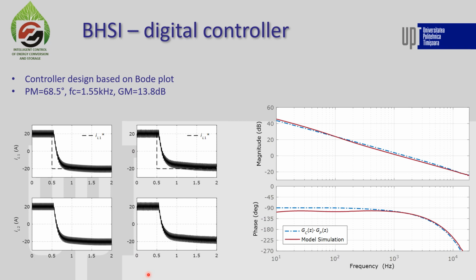And this might not look like experimental results, but they are experimental results. And there is actually a difference in the transient operation here. The simulation is a bit faster. The model in simulation is faster than the model in the experiment, probably because in the experiment we have a few more parasitics which we have to take into account for closer results.